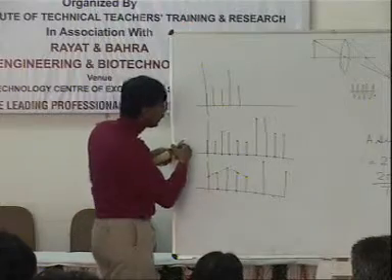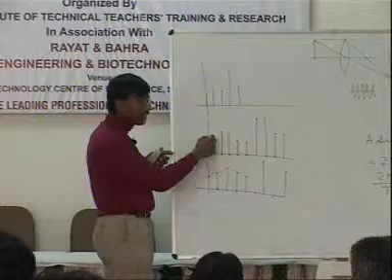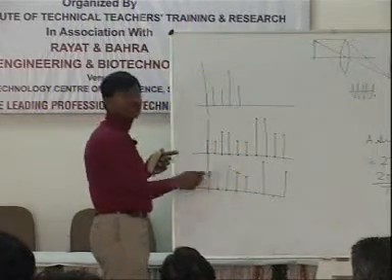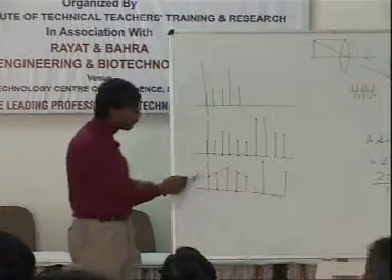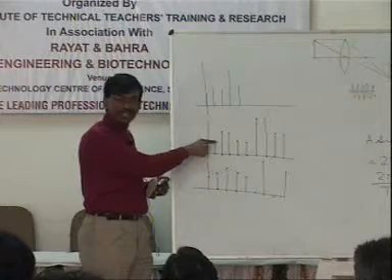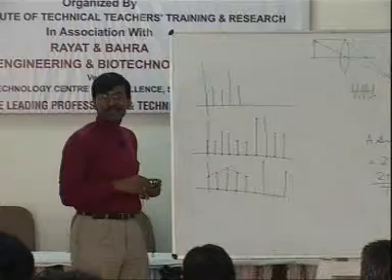Okay, those in communication would call this a zero order hold. Alright, it's basically the previous sample you are holding. This is called a zero order hold. What is this called? This is called a first order hold, because this is a line. But still you will recognize why this is smoother than before. This does not introduce any new information into it.